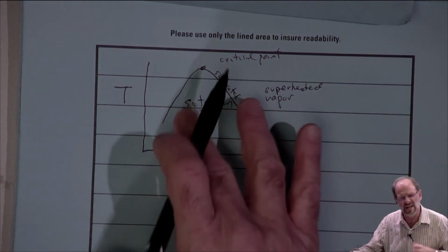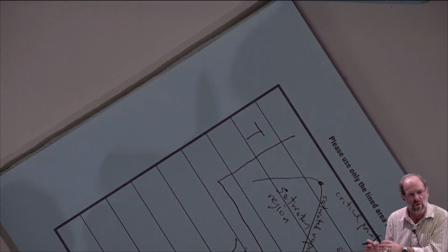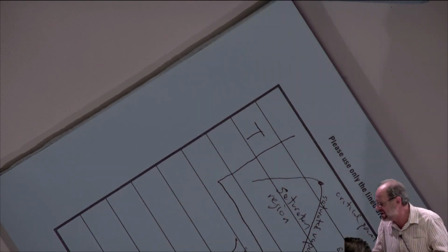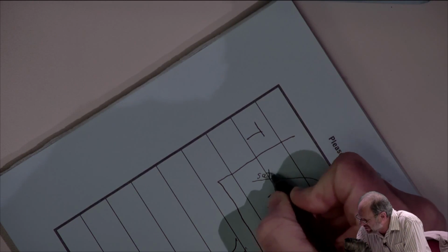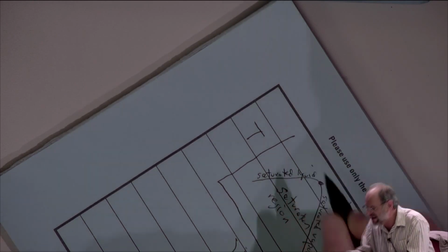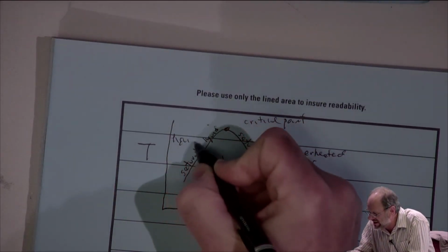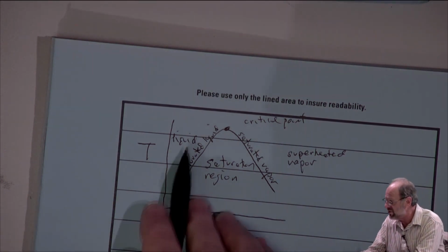So we're going to do the same thing over here on the left-hand side. When we just barely get to the point where the liquid water is just beginning to vaporize, we're at exactly 100 degrees Celsius, 1 atmosphere, yet we're still all liquid water. We call that a saturated liquid. Now, anything to the left of the saturated liquid is still a liquid, but again, we want to use terminology so we can make a distinction between the two.